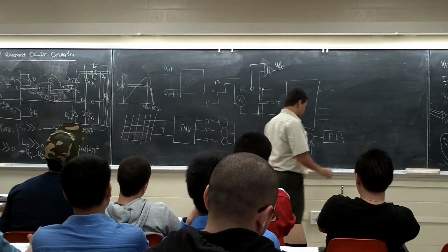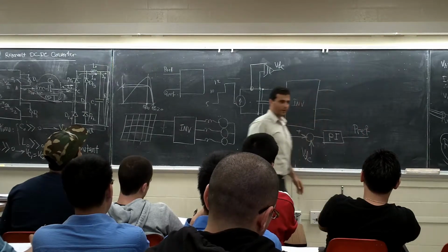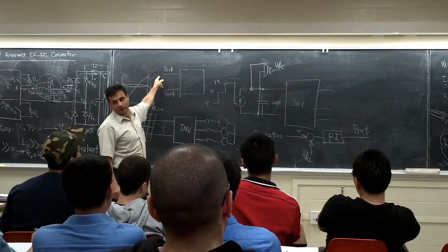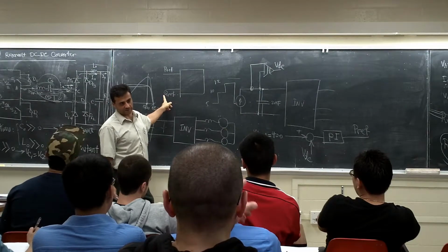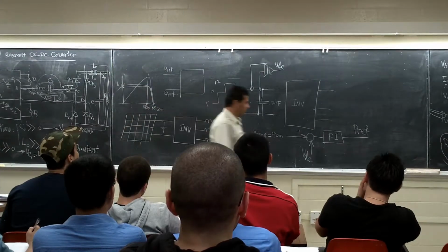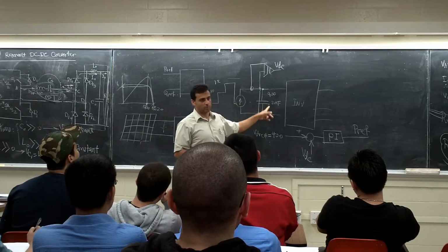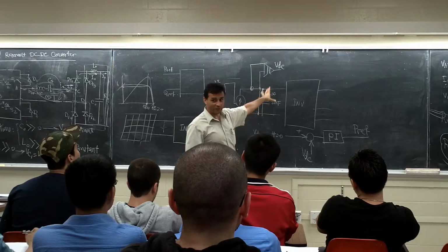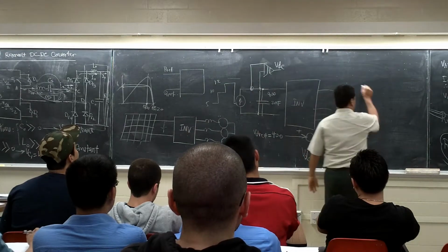And now, connect it to whatever you have already, right? And QRF is 0, 1 unit power factor, right? QRF is, in this case, in phase 4, 0. So what is going to happen? You pre-charge this capacitor to 400 volt. When you are simulating this, put 400 volt here, pre-charge. In reality, we have to do all these things by circuit, but here just put the numbers. Now, when you run this simulation, this is what you need to check.